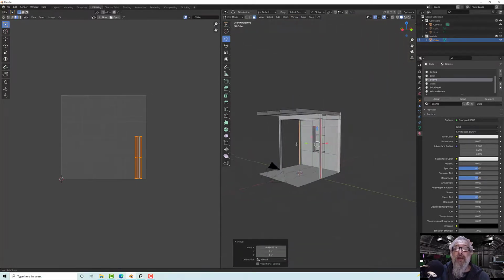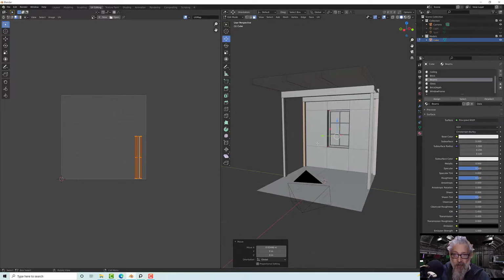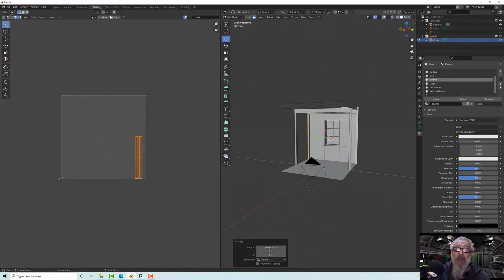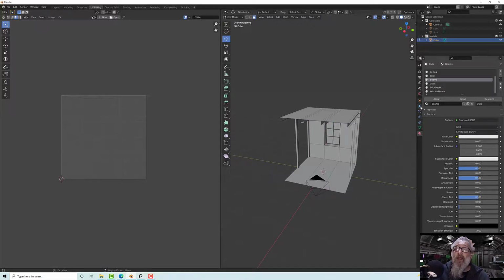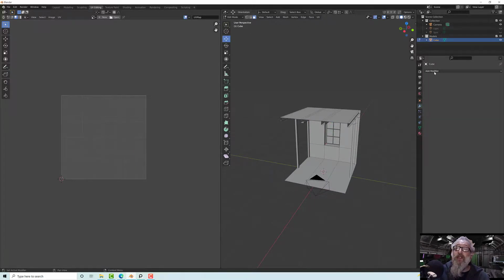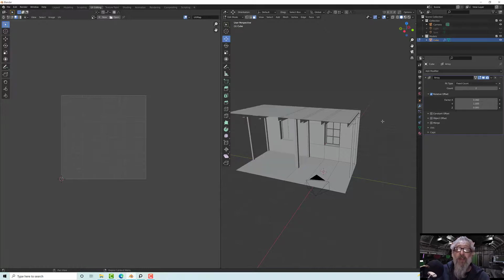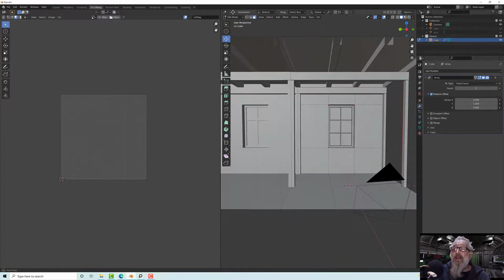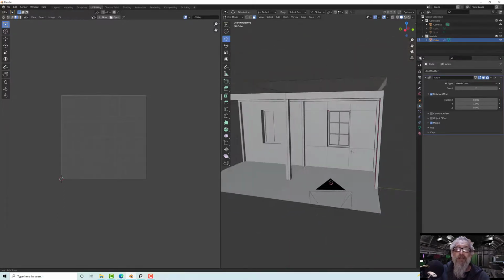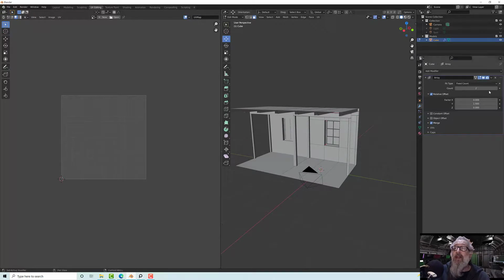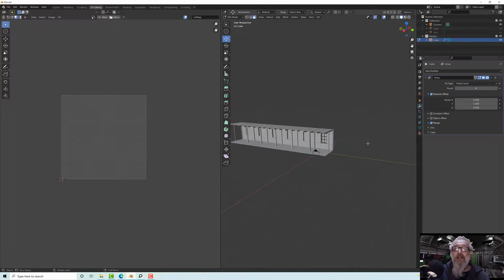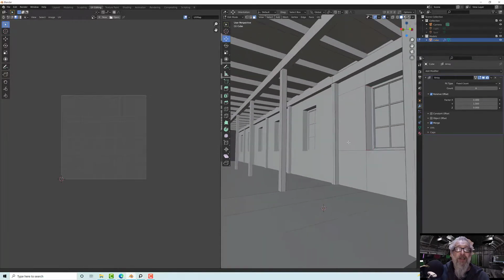Now I shouldn't have any welding issues where things weld to things that I don't want them to. Okay, so now on the modifiers tab, I'm going to add an array modifier, and I'm going to set the X factor to 0 and the Y factor to 1, and that, if I hit merge, should create us one deep, as it were. So if I increase that maybe to 6, I now have a nice kind of long